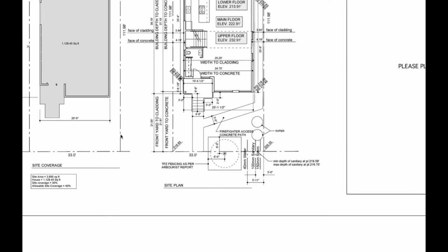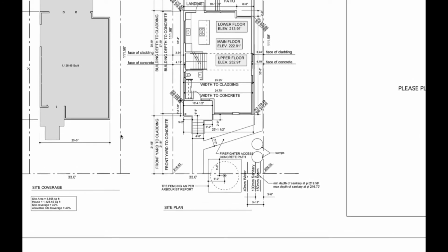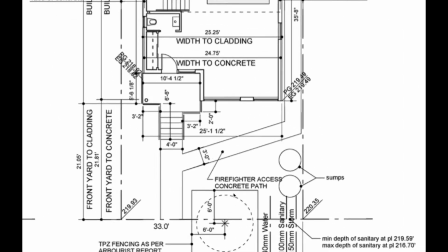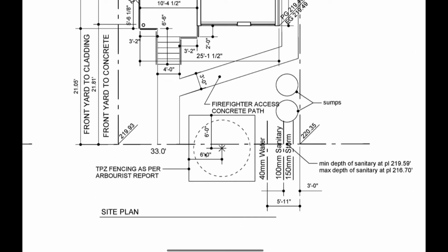Okay, so on the site plan here on the third page, this gives us a lot more information about the nitty-gritty and what we're getting into in terms of construction. It gives us our first really good look at the building. So we'll start, the street is up here, and we'll zoom in a little bit. We see there's going to be a tree here. They want temporary fencing, which is always good to know.